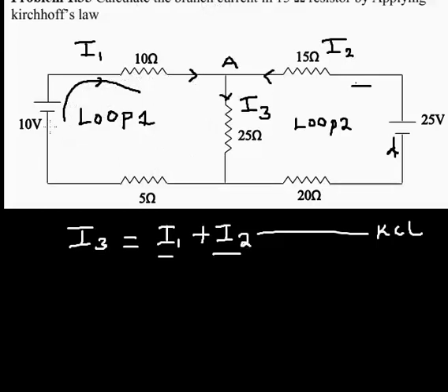So that's going to be a flow from 10 volts, and don't forget our sign convention. If you are going around the loop, once the current reaches a particular resistor, that particular terminal is positive. So for this 10 ohm, here is positive, here is negative. As it enters the 25 ohm, the first terminal is positive and the other is negative. It flows again, and as it reaches the 5 ohm, here is positive and here is negative. So let's flow with the law.